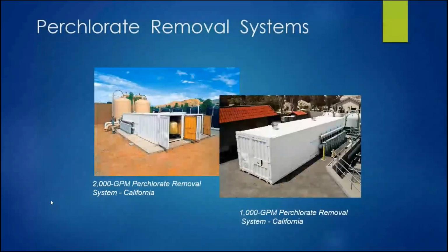We also do perchlorate or perchlorate and nitrate treatment, depending on what is in the well water. Perchlorate has become a major issue, so has PFAS. And all of those can be regenerated, but the most economical process is typically using it in a disposable method, in which the resin is thrown away after absorption. It's usually incinerated.